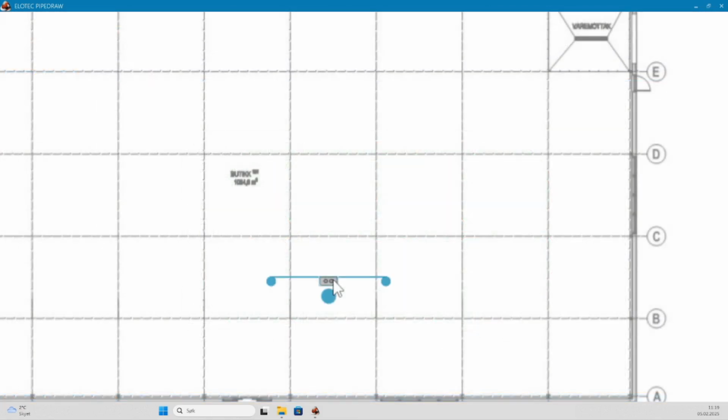When you click on the aspect, you get access to 3 circles, 2 on the side, and 1 large in the middle. Without clicking on the circles, you can simply drag the aspect around in the scene to place it on desired location. To rotate the aspect, use the blue circles on the arms to adjust its orientation. If you hold down Shift while rotating, you can rotate the aspect freely, independent of the predefined axis.